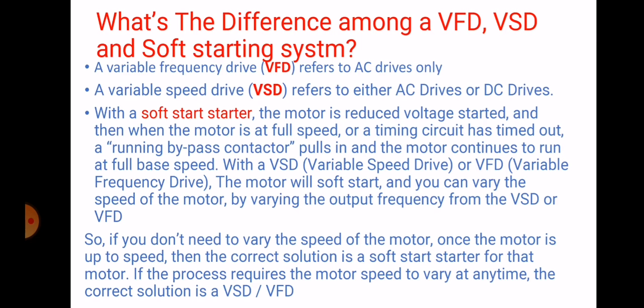This is the question, what's the difference among VFD, VSD, and soft starting system? There are three systems: VFD, VSD, and soft starting. What is the difference among these three? The VFD is a system which refers to AC drives only, and the VSD is the system which refers to either AC drives or DC drives.